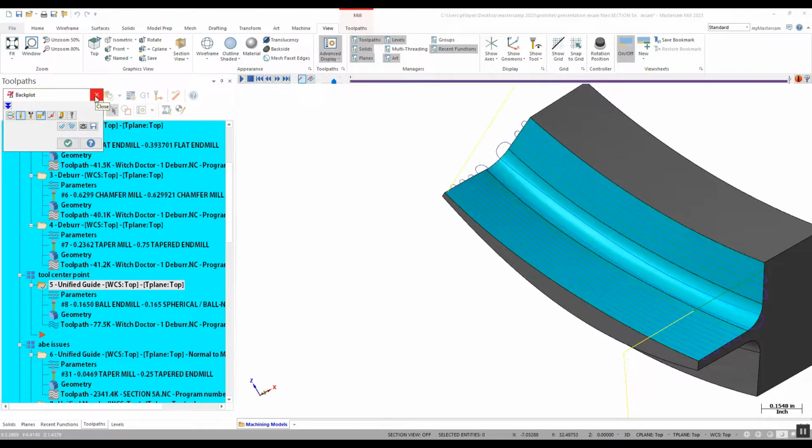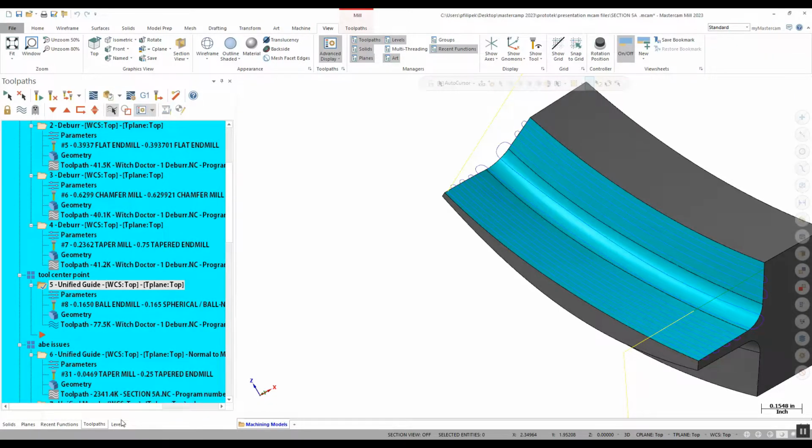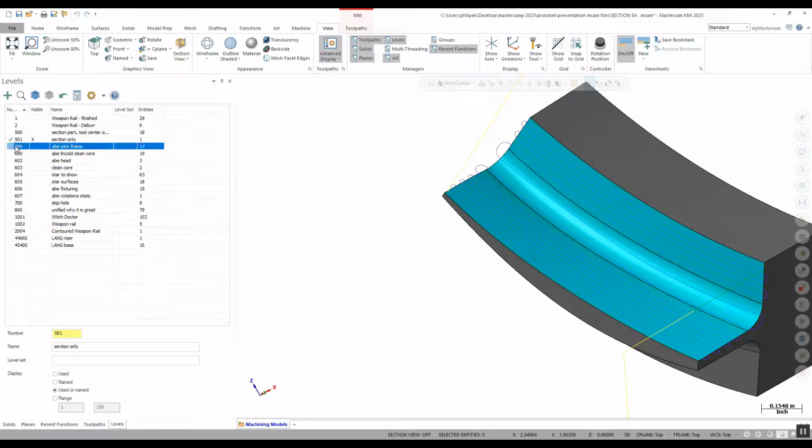if you're running into these situations, which a lot of people do run into. People used to lie to Mastercam and say the tool is a little smaller than what it actually was, so it didn't see the collisions on multiple sides of that ball. You shouldn't have to do that now if you go back with this method and try to utilize tool center mode. So try it out, see if it can help you in them odd situations that you do get into.